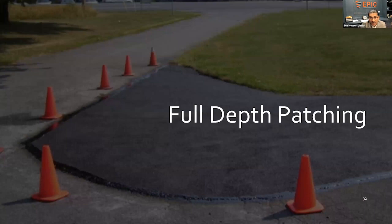So then we go over to full depth patching. From a full depth patching standpoint, this is pretty permanent, as I'm sure we can all imagine. These are going to be localized areas. You're going to be looking at full depth patching for mainly your structural components. And if your cracks start to get too bad, if your PCI number starts dropping too low, full depth patching is going to be considered and probably likely the only option at that point in time.